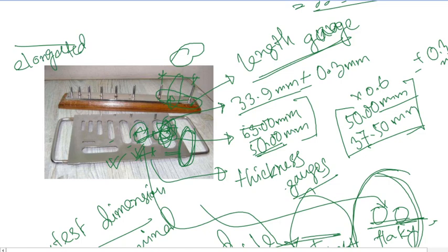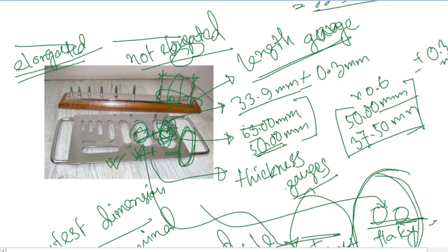Okay, and if you are able to pass it in all possible directions, and you are not able to restrict it through these two stands, then keep it as not elongated. So finally, the total percentage of elongated particles will be the elongation index of that sample, keeping some exceptions which we'll be discussing now. So in general, the percentage of the elongated particles will be the elongation index.